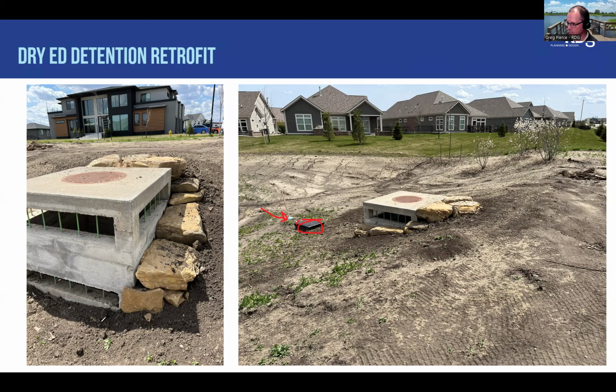So instead of having an open top, it's just kind of a more traditional area intake. There's another one on site that only has the upper openings. This one had both a lower and an upper opening that was designed to control the more moderate and large storm events. So the 1 year high water level doesn't get above this lower opening. Once it got above that level, it could start to access that lower opening. And when the level got up to about the 25 or 50-year storm, then it started to access these upper openings and allow flow into that.